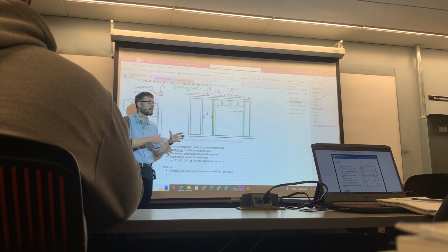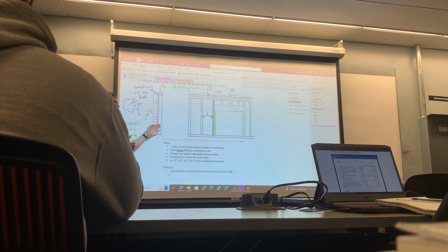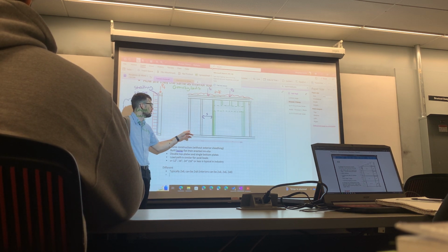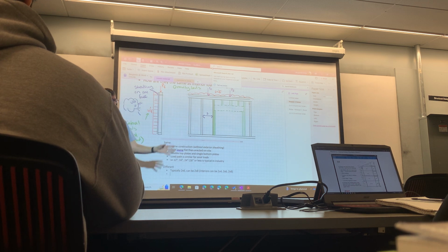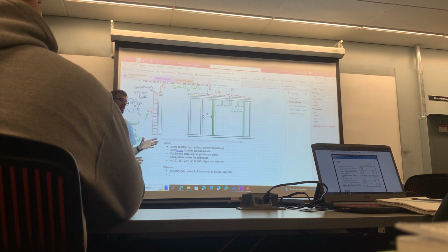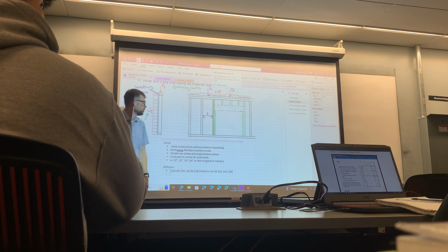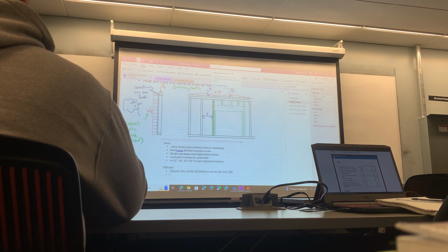Thermal bridging. So no matter how deep you make that cavity, you're going to have those studs, and then the architect will ask you to space it out to 24 or 36 inches, and you'll come back and say, no, we can't do that, right? So that's why now architects are going to this whole rigid insulation on the outside, where it's completely uniform, but that's an aside.